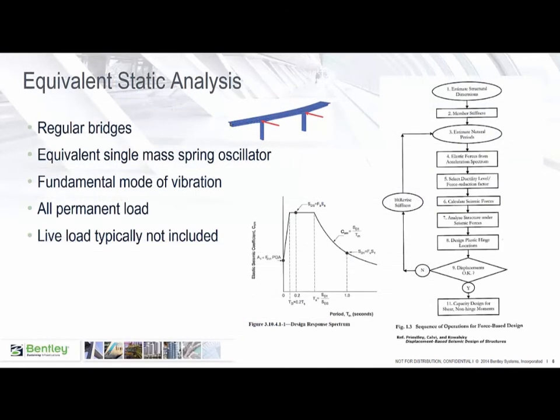Equivalent static analysis. In the equivalent static analysis method, the structure is idealized as a single mass spring oscillator. Cross-sectional dimensions and equivalent stiffness are estimated. All permanent load is lumped in a single vibration mass. Typically, inertial effects of live load are ignored.